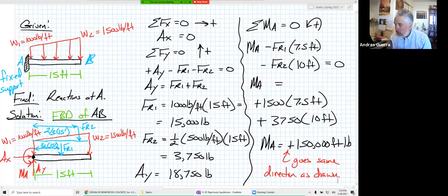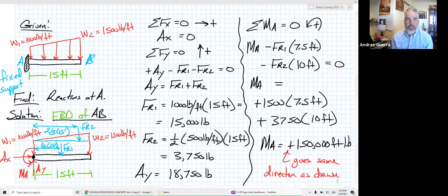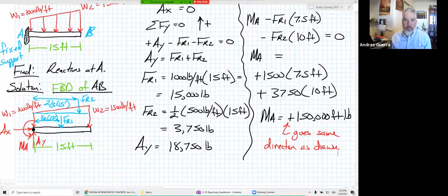And then, would we ever have to include the weight of the beam? Yeah, we could ask you to include the weight of the beam. In this class, though, if we don't tell you the weight of the beam, just assume that it's 0. In real life, absolutely, we would include the weight of the structure in this calculation. The weight of the structure sometimes is pretty small, so for us, it's reasonable to neglect it and still get an answer that means something. Good question. Sometimes we will give you the weight of things, but if we don't, just assume that it's 0 or negligible.